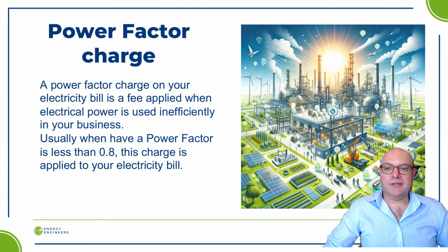Power factor is a measurement of the efficiency of your electrical usage. A value of less than 1 indicates losses in your system. These losses are created by inductive and/or capacitive loads. These are all loads except for resistive heaters or incandescent lights.